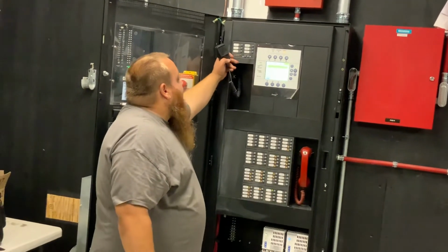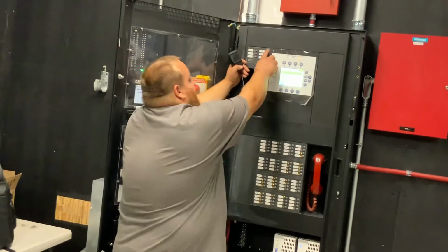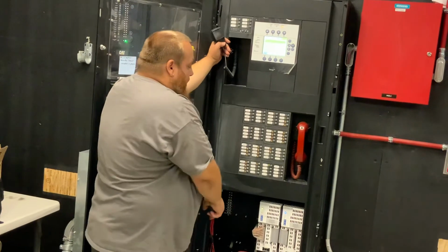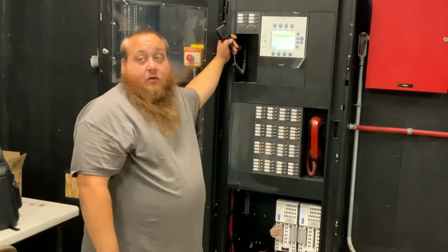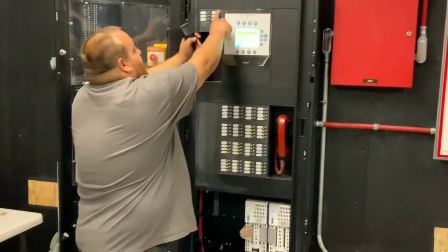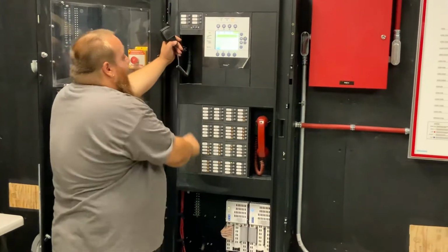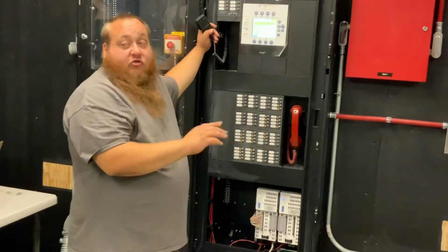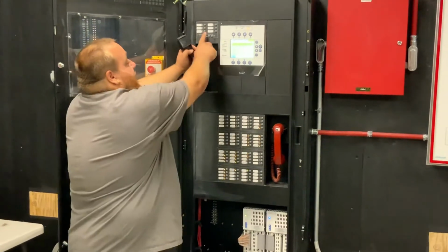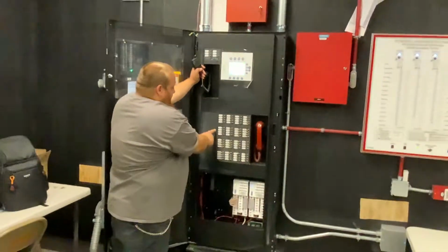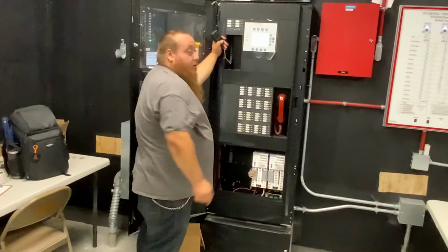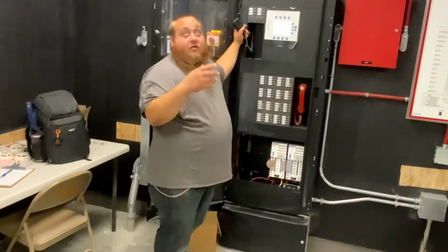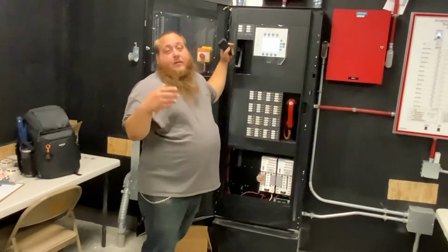Then you have your selective page. You select that button, just like these other buttons as well. Then you can select what floor or what elevator you want to speak to. Then you have select evac. You hit that button, you would select what floor you want people to evac on, just that floor. Same with the selective alert. You would select your button, and then what floor to tell them, hey, you have an issue. Could be a water leak, saying, hey, if you see any water from the building. Could be anything like that.